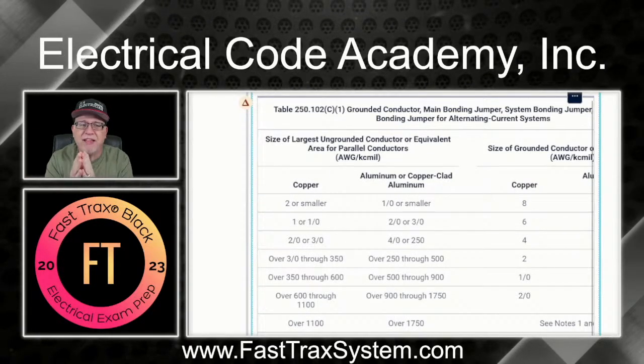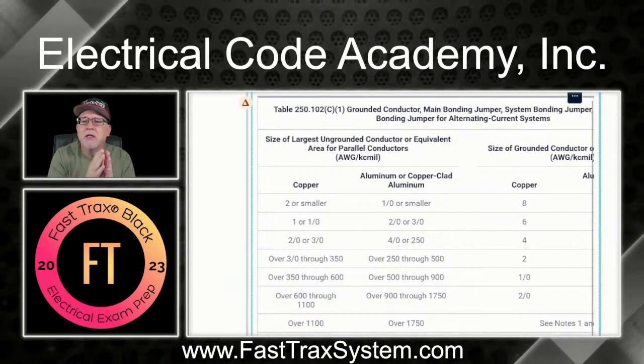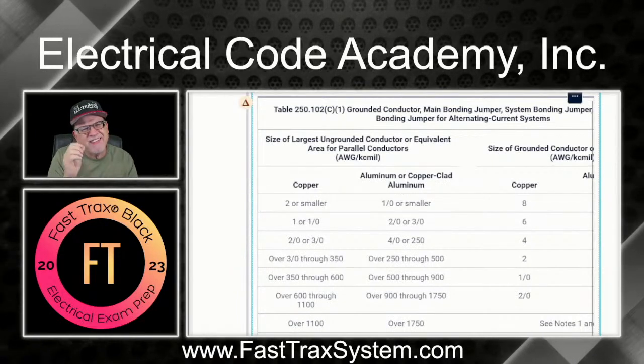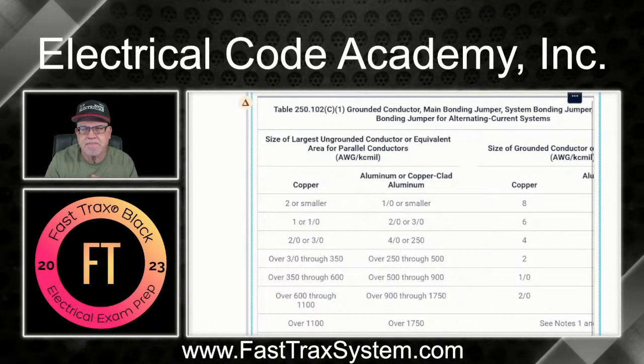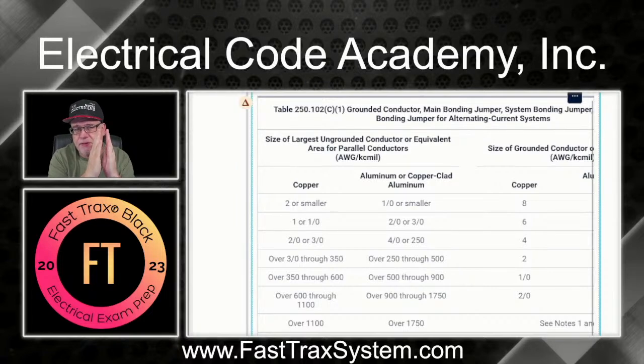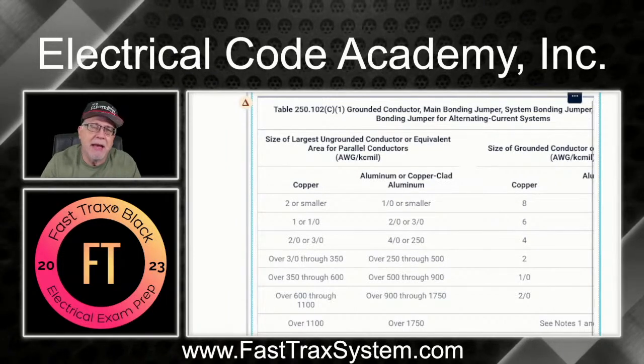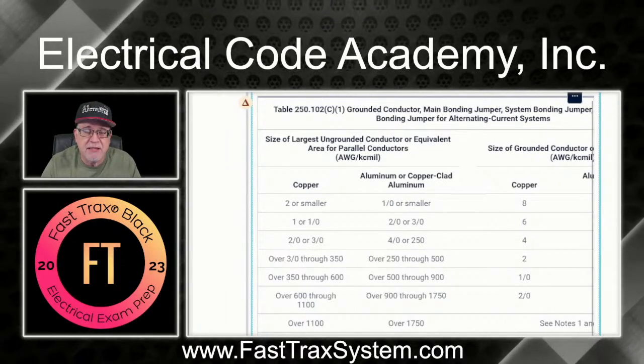We're just going to take the largest ungrounded conductor from each set, which is, let's just take A phase, because they're both the same, they're running parallel. So let's say we ran 2 sets of 350s through one raceway. Then that's going to be 350 times 2, because that's A phase, you have 350 for each. Add them together, that's the summation, and that becomes 700 kcmil.